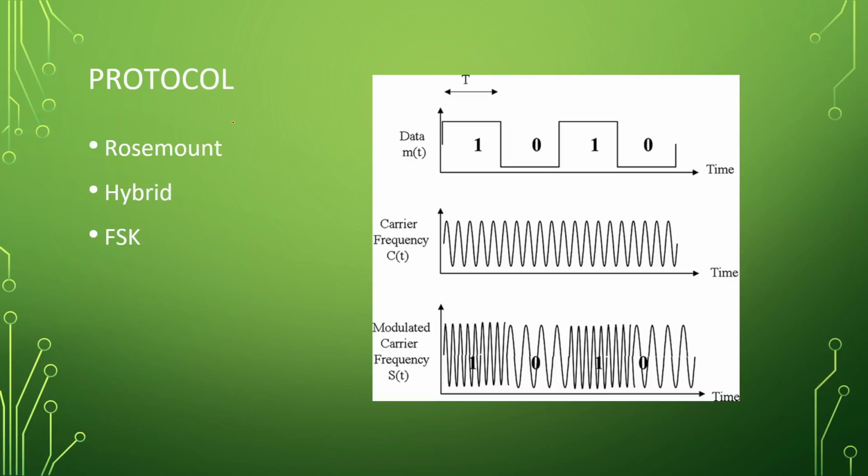And then we talked about FSK, or frequency shift keying, where we are taking digital data, zeros and ones, which is what we've got going on up here, and we are combining that with our, what was it, I think the 1 was 1,200 and the 0 was 2,200.